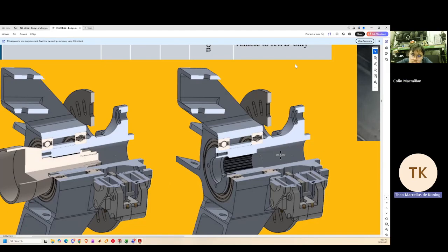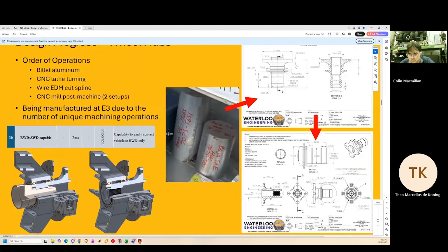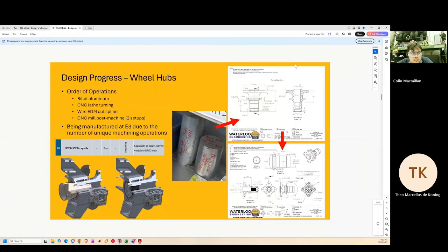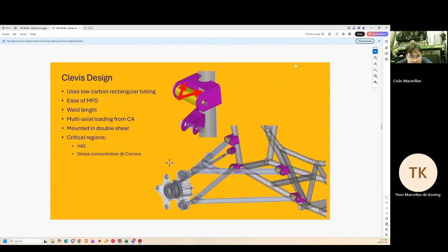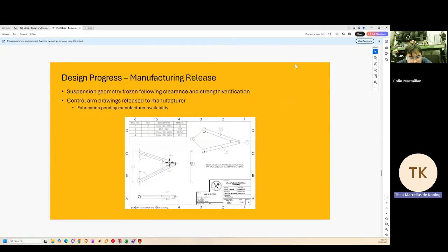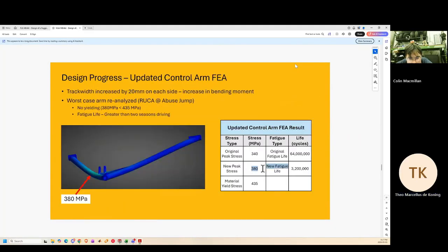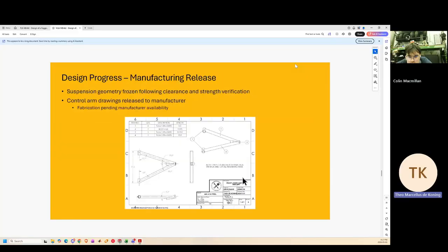So you basically shifted the contact patch and wheel center out by 20 millimeters. And so we recalculated our forces and reran FEA, and it was a tiny bit different. So we said, all right, whatever, we shouldn't bother doing a new analysis, because the difference is so small.